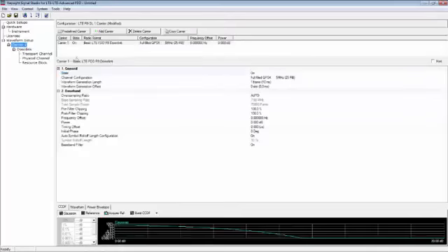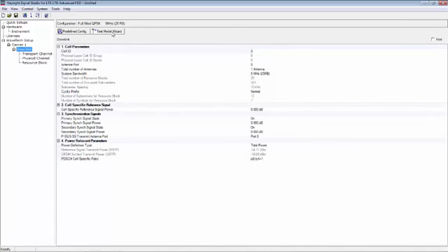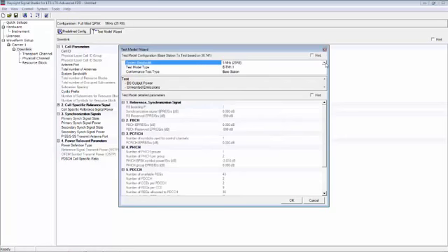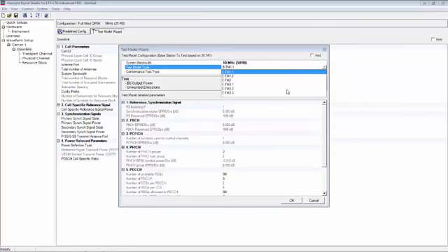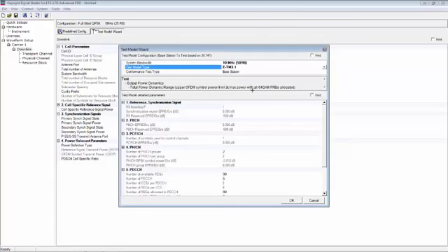Next, we are going to start with the default basic LTE downlink carrier with a fully filled QPSK 5 MHz 25 resource block signal, and we are going to modify that using the test model wizard. First, we'll set the system bandwidth to be 10 MHz, and we are going to go into the test model type, and here is where we can make the selection of E-UTRA test model 3.1.